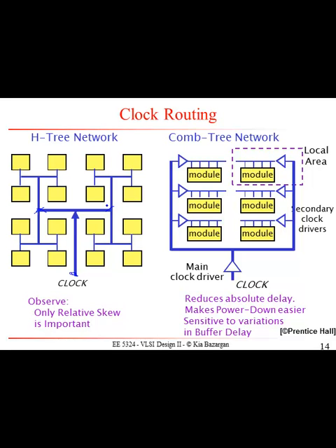these points are symmetrical. So whatever width of the wire of the clock tree you use is going to be the same on these two. And then if you look at it, all these points are getting the signal exactly at the same time. And of course, I'm assuming here that you're not dealing with any process or thermal variations. But if you ignore PVT, then every single flip-flop that is shown in this structure is going to receive the clock exactly at the same time.